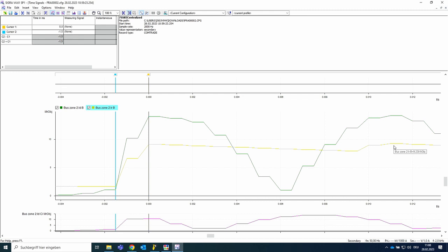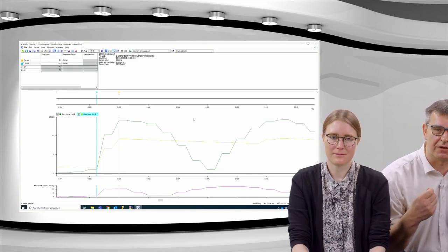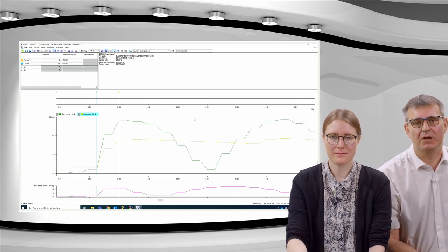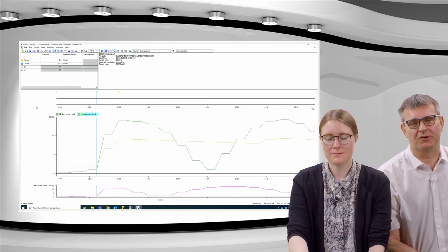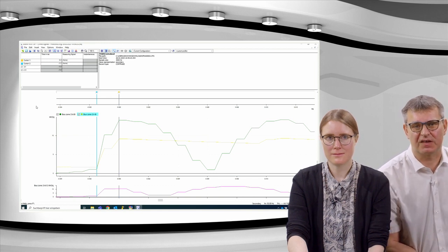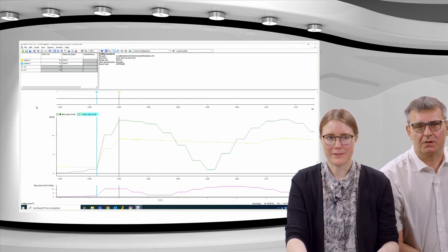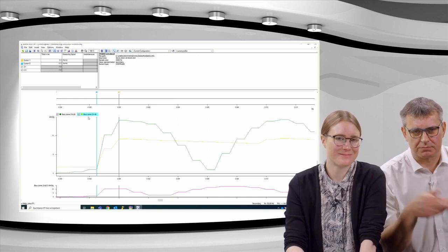But still more, we are seeing here not the modified stabilization current, we are already seeing the modified stabilization current multiplied with the stabilization factor. That means if the differential current is above the line in the fault record, we can directly state we are in the tripping area. So as soon as the differential current is above the characteristic of the modified stabilization current multiplied with the stabilization factor, we can say, okay, we are in the tripping area. Okay, so I will continue.